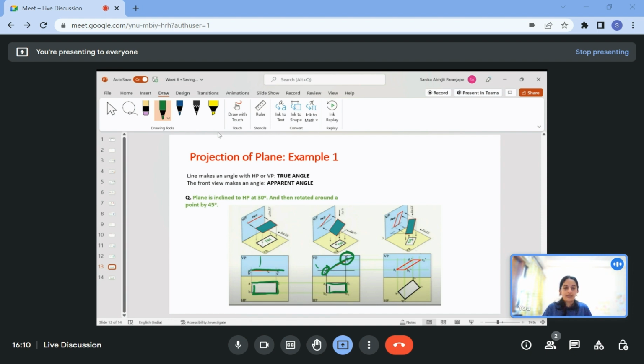So there is a difference in rotating it with respect to a plane and a point. Here now, if you want to rotate the whole surface such that it makes 45 with the vertical plane, then you will have to rotate it along this line, this edge. But they have done a simple case where they are rotating this line like this. So when you do this, only the projection in the top plane gets tilted like this.